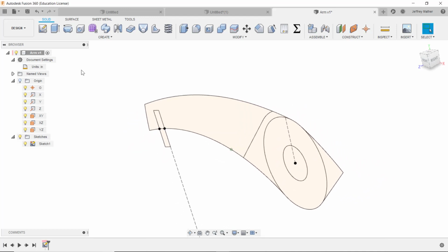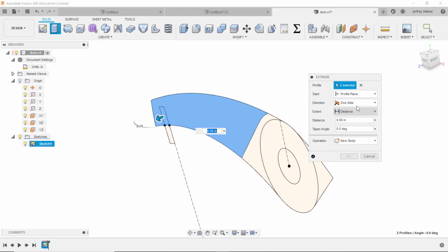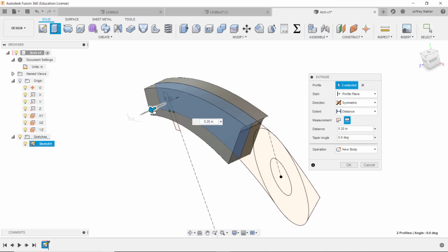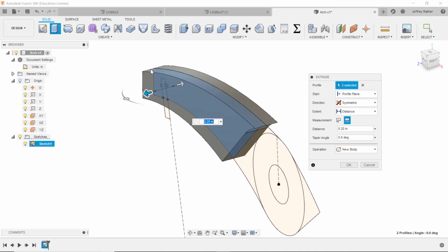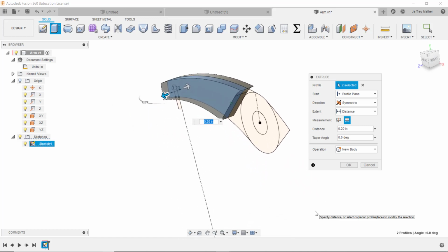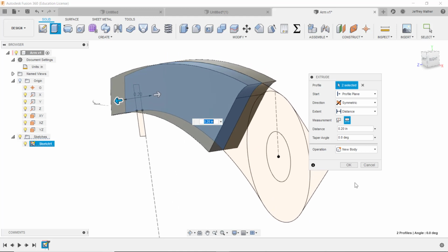When you do your extrusions, do the extrusions mid-plane, so that you always look for symmetry about the origin planes, and then we'll do that, and then do these ends, these small fillets, as fillet features rather than as sketch features. So that should give you some ideas on how to do a fully defined sketch as you go along.